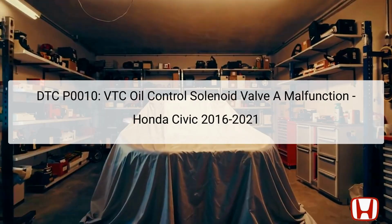The DTC P0010 indicates a malfunction specifically in the Variable Timing Control (VTC) Oil Control Solenoid Valve A of the Honda Civic from 2016 to 2021. This component is crucial for regulating the flow of engine oil to the VTC system, which adjusts the timing of the intake and exhaust valves for optimal engine performance and fuel efficiency.